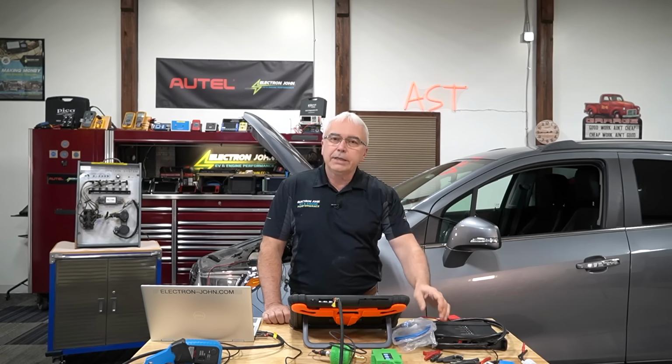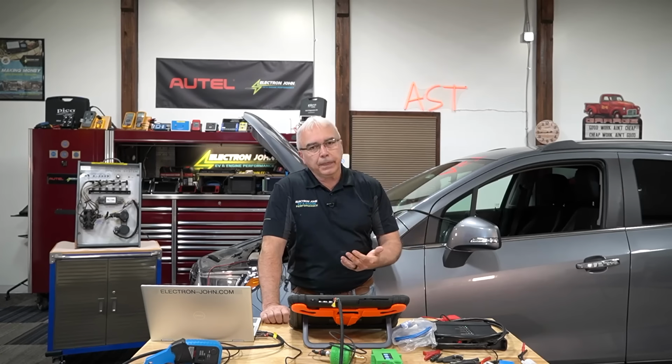So for example, if I had a no start on a modern-day car, I could have a bad battery, I could have a bad starter, I could have all the normal stuff. I could also have a bad sensor that's picking up anything from the key fob to the actual push button on the dash. How would I normally test that? If I didn't have that, I'd probably scan it for codes, maybe use topology screen, scan it for codes, and if I was lucky, I had a code to go on, right?